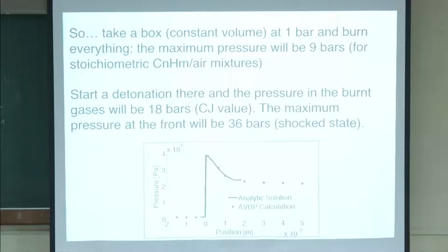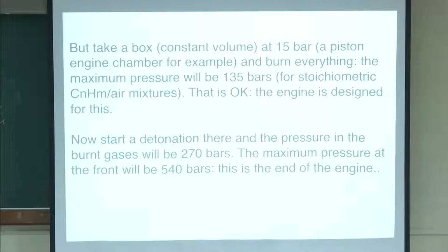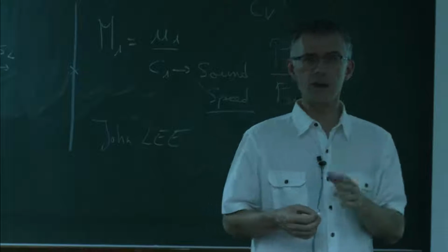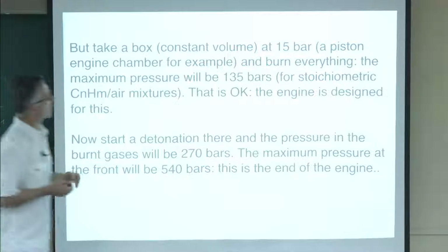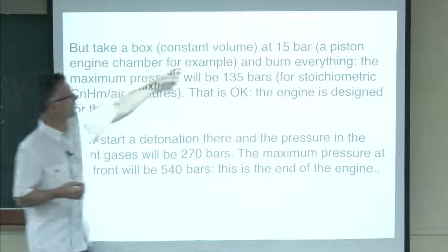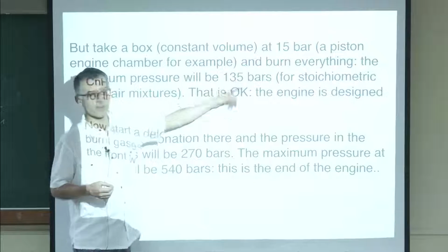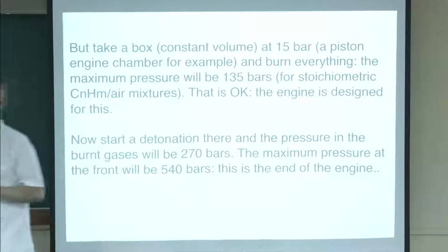So for the structure, now it's getting a little bit more complicated. But suppose now you're not doing a simple engine like that one, you're doing a true engine. In a true engine, you don't start at 1 bar, you start at 15 bar. So if you start with 15 bar, then you expect, if you burn everything, to have 15 multiplied by 9, which is 135 bar, which is already a big pressure.